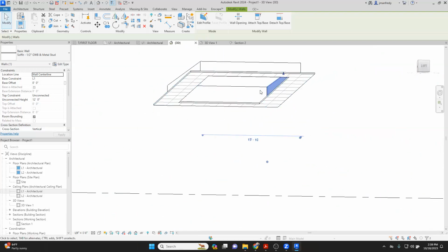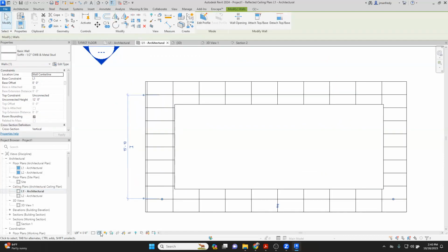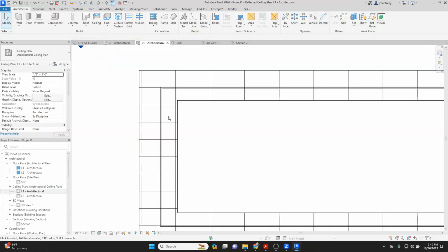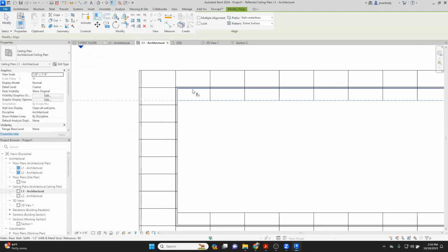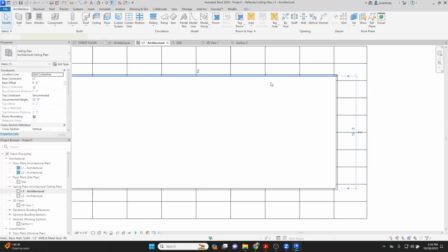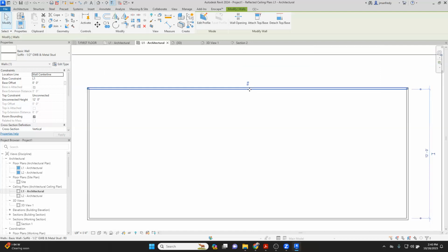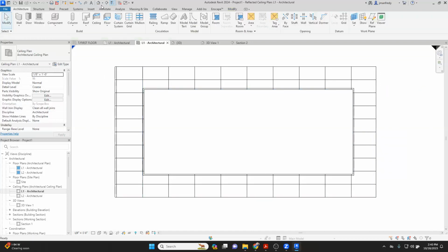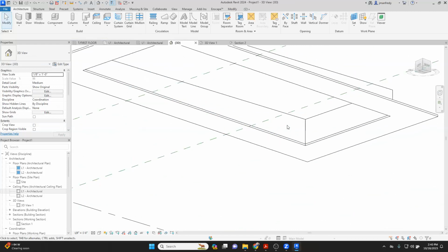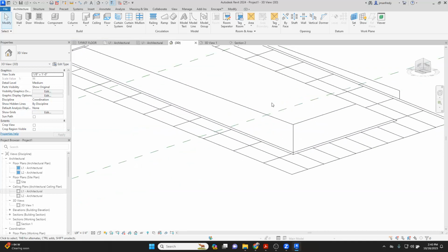And or you can line it up and make it like a raised ceiling. Just line that up with the edge of the opening and make it a raised ceiling. Usually you can just simply make this transparent. You can see where the walls are, right? So if I align these edges here, like on the walls, you see the metal is back here facing the back, so that's good. The gypboard's facing the front, so that's good. You need to test all the edges. But there's a raised ceiling. Like this is lower ceiling, and it goes up to a higher ceiling up here. So that's how you would do it.